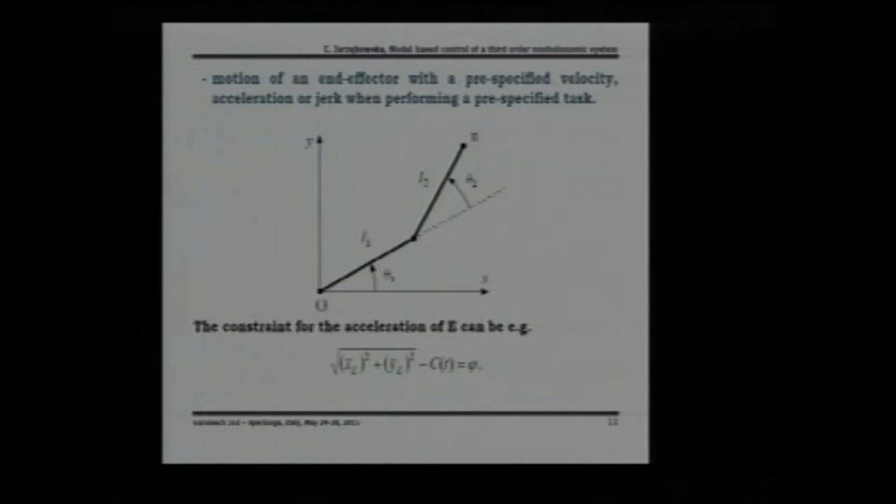Can you see that the curvature and its derivative is here? So they are definitely higher-order non-holonomic constraints. And if you work on vehicle performance, ride quality properties, you have to handle these additional requirements.